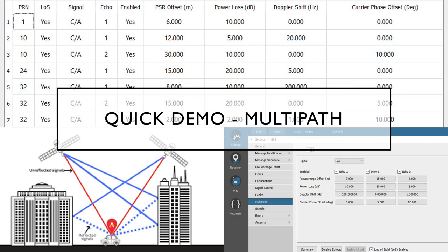One reflection isn't always terrible because typically the signal is circularly polarized. It's right-hand circular polarized, so when it reflects, it bounces off as left-hand polarized. If you've got an antenna that's tuned for right-hand polarization, it will lower the signal power if it's left-hand. But then if it reflects twice, double reflection, it goes back to right-hand, and that can have an effect. And these are the sort of things you need to think about.